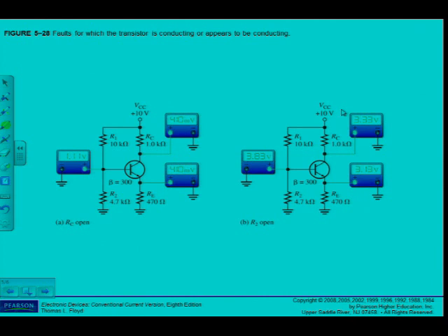Alright, so if I go and look at this circuit, and that resistor, for instance, is open, again, there's going to be no IC. What am I going to measure at VC? We've done the calculated values at VB. So at VC, when I'm going to measure from VC to ground, what should I measure? As I've calculated here, VB minus VBC is that 1,11 volt minus 0,7 is going to be 0,41 volts. Like indicated here, 410 millivolts on my multimeter.